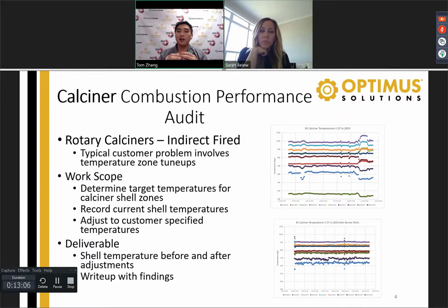So we reduced that variance from 600 degrees to 300 degrees. So this is something that we can show a before and after. We can show the quality metrics, which is temperature in this case, and we go on from there. Typically, in these cases, you're trying to get a certain temperature, and these have multiple burners, 9 burners, 12 burners, 6 burners. It's a lot.